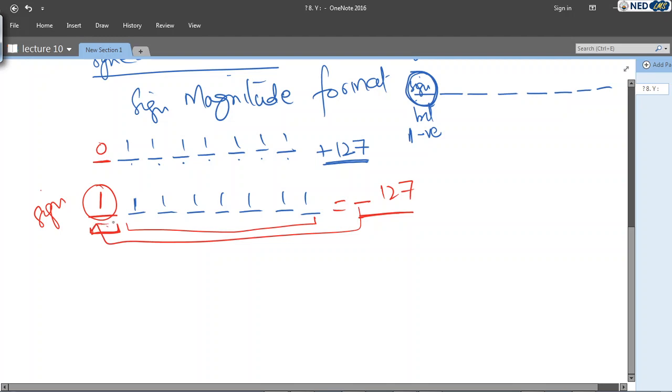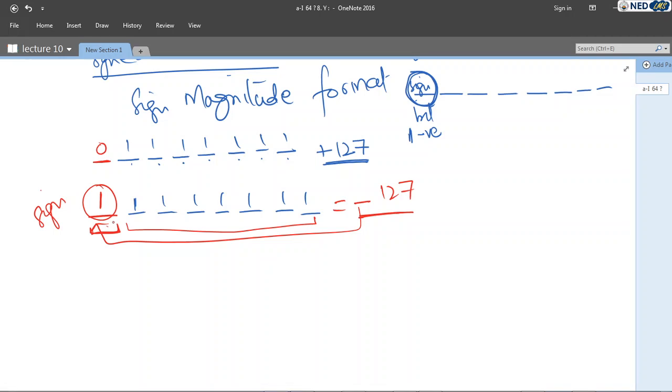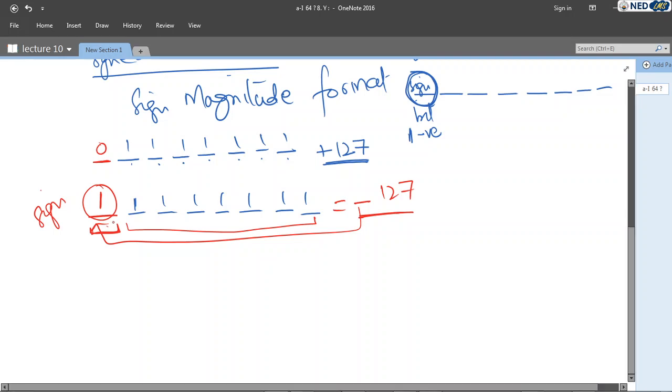This sign magnitude format is useful when we are talking about analog to digital converters, in which we convert the analog values coming in from some sensor, which is giving us a continuous time, continuous valued voltage, into digital numbers, because a computer has finite memory and each memory is of finite size. So we need to convert it into discrete time, discrete valued, and you are going to see that in your signals and systems and DSP course.